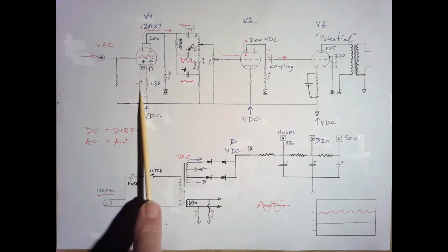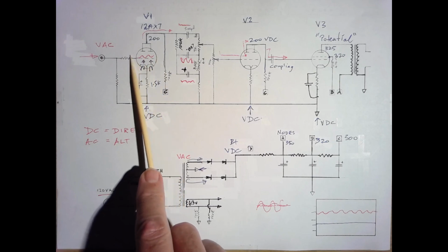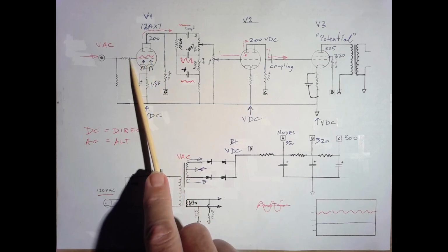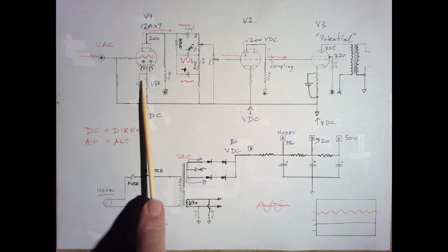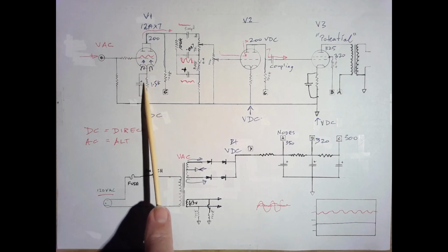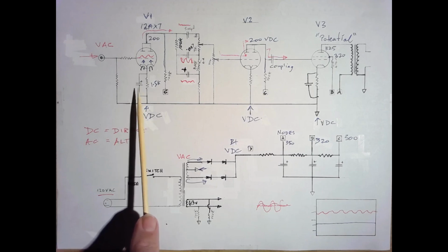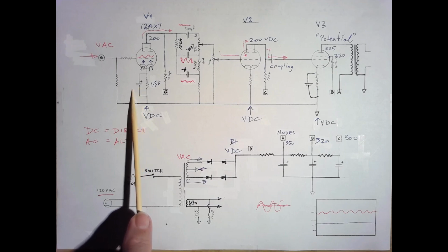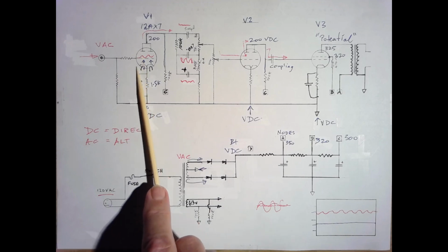It responds because it's an AC path here. It's in resonance to some extent with our AC signal coming in. It's understanding almost and interpreting the different sine wave signals that are coming in here. And this capacitor allows some freedom in the way these electrons can zoom according to the signal that comes in. The size of this capacitor can be changed enormously. A standard size is 25 microfarads. It's quite common to see a 0.68 microfarad in some Marshall preamp stages because they don't want bass. They want a bit more warmth and they want maximum gain.